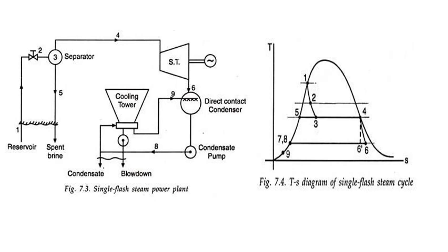And here, as you see, the steam after working, since it is coupled with the alternator, this stands for the alternator, is sent to the direct contact condenser, like a deaerator, and after that it changes phase and a condensate pump is used, because the condensate pump makes the water available once again to the system.